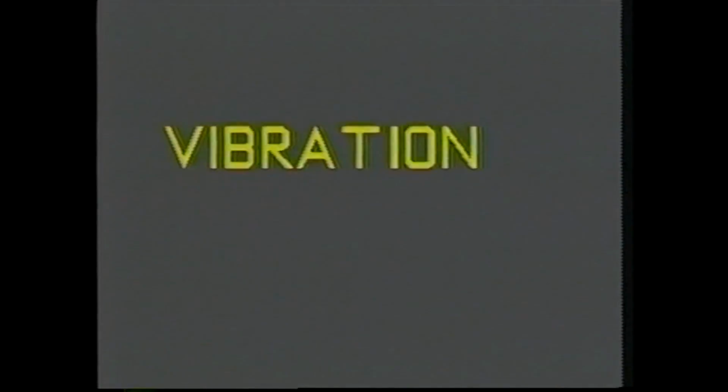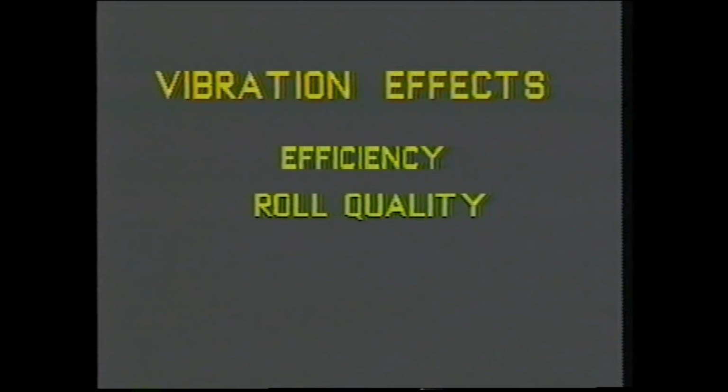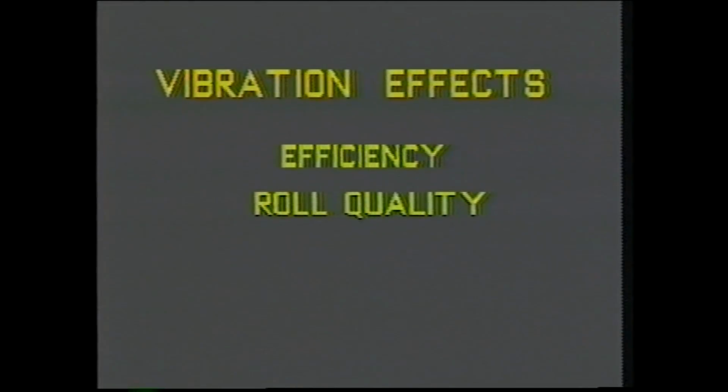All winders vibrate during operation. The severity of vibration may be barely noticeable or a minor annoyance. However, in many instances, winder efficiency can be reduced because slower operating speeds may be required in order to avoid snap-offs and thrown rolls. Roll quality can be reduced by web breaks resulting from unstable unwinds or tension control, and by rough slitter cuts resulting from slitter vibration.